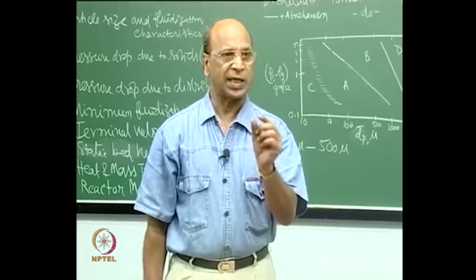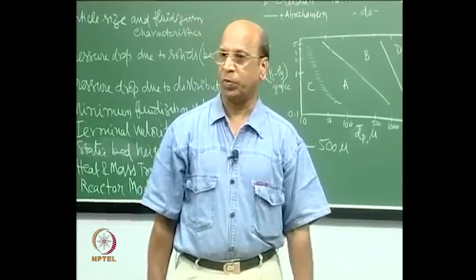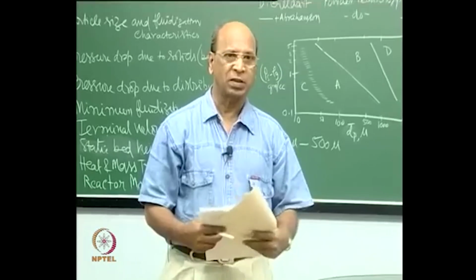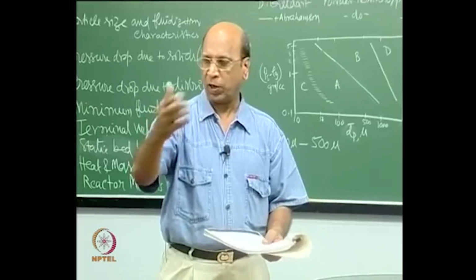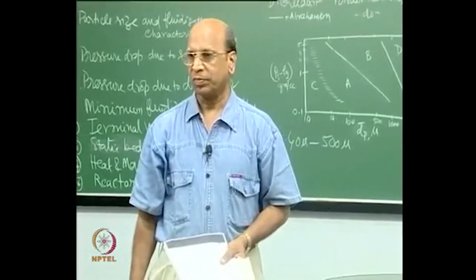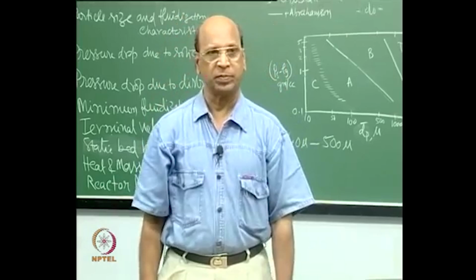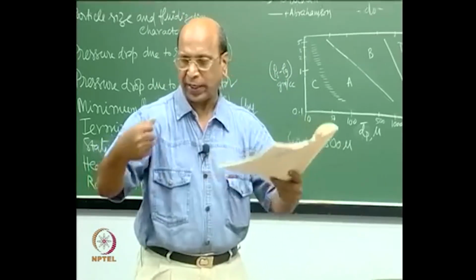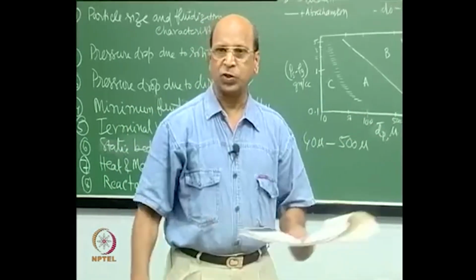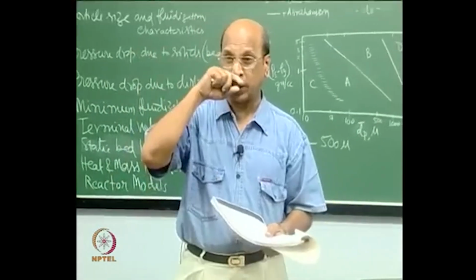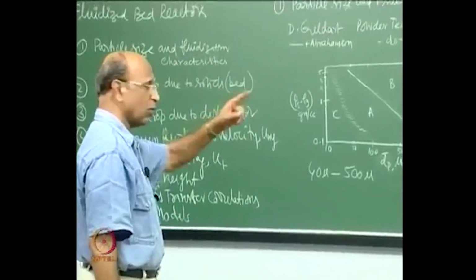The moment I have that kind of particles, which is the starting point, then I will know, oh, maybe I will have this kind of fluidization for me. So, I better go for a shallow bed. Shallow beds means very shallow, if L by D is 0.4 or 0.5 or 0.2, that is a shallow bed. Why? Because for large particles, if you have very deep beds, fluidization is very difficult. And when you are pushing the gas more and more for getting fluidization, suddenly they explode, because you will get exploding bubbles, channeling may occur, particles may be thrown here and there, very high aggregative fluidization, which is not uniform fluidization, right.